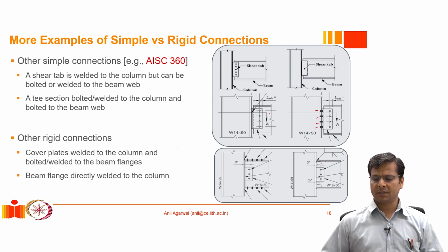So considering all of these, these parts cannot effectively transfer the shear force demand. So these welds are not really meant to transfer the shear force, and the shear force, which is anyway highest near the web or the centroid, that is the neutral axis, it is much more prudent to provide shear connection near the neutral axis of the beam in both cases.